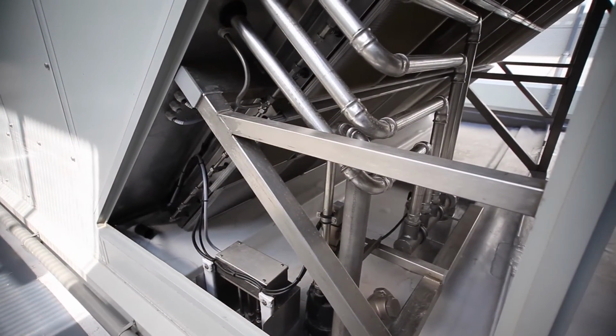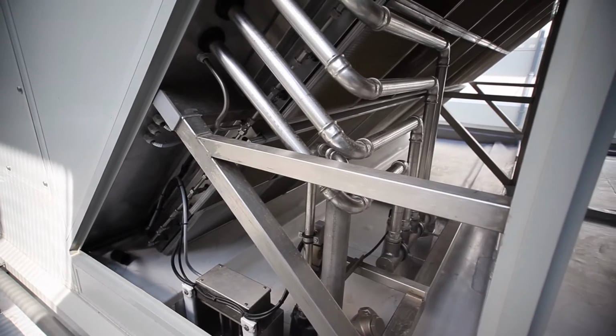So at Lon 5 we're using indirect air cooling technology. Essentially it's an all-air system which takes the outside air and uses that to cool the recirculating data hall air, but it does it indirectly, so you never get outside air coming into the data centre. There are plate heat exchangers in the air handling units with adiabatic cooling as well to assist in peak summer months.